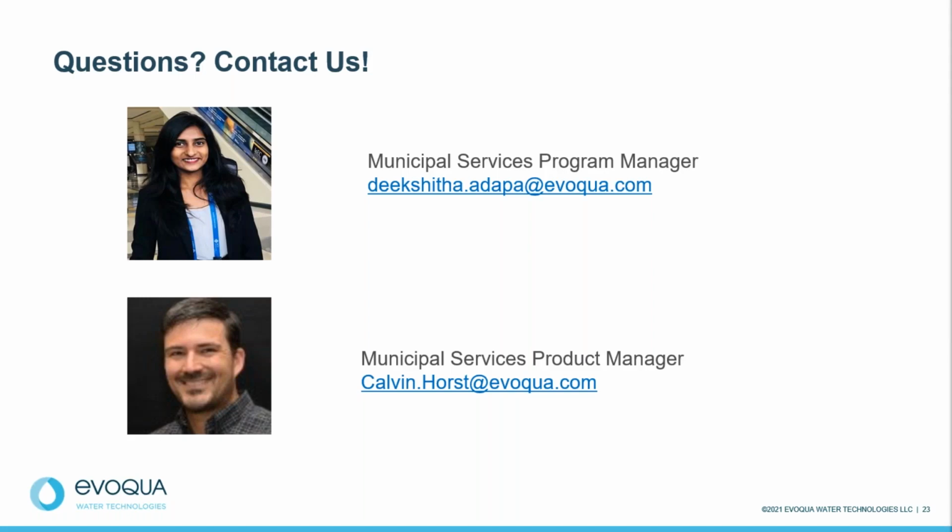So we at Evoqua have a variety of different methods for dosing chemicals into a wastewater collection system for odor control. When we talk about advanced dosing controllers, we're specifically referring to devices that have remote telemetry and are able to be operated remotely. So in practice, one of our trained service technicians would log into our web portal and have the opportunity to manipulate dose rates remotely.